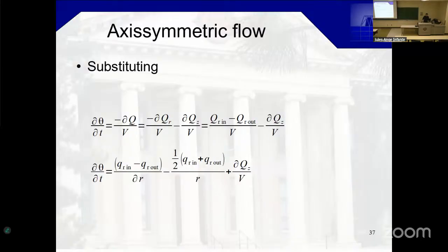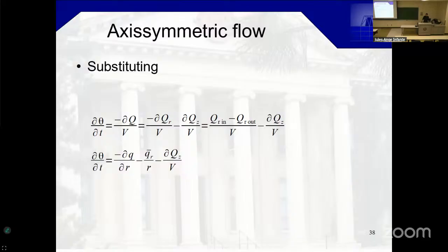And you end up with an interesting term by just doing a little bit of algebra. Now, we end up with qR, which is the Darcy flux, so K radial, KR, dH over dr. And so if we replace in terms of hydraulic head, we have K radial direction times d squared H over dr squared.